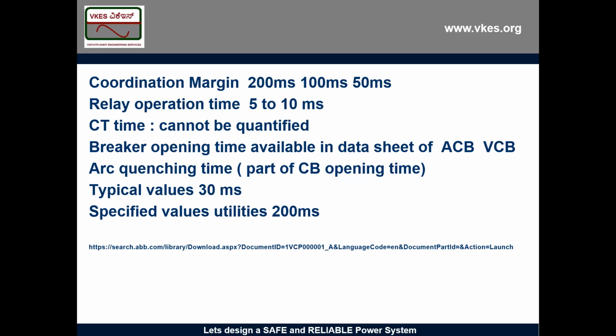Now let us say I'm doing a coordination study for the BP Texas refinery. The entire plant has almost the same type of relay. So there you fix the coordination margin and you follow it. Don't change it. Okay, clear, sir? Yes. Okay. So the coordination margin, yes, sir.